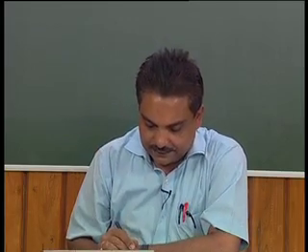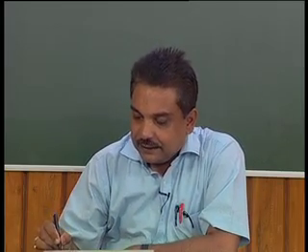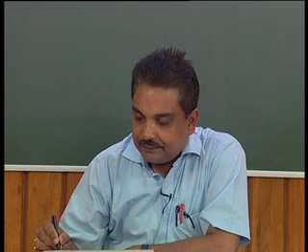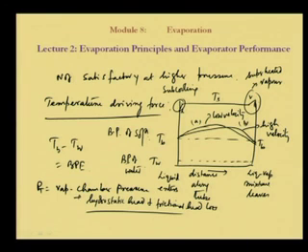Before I tell about that, one thing I should say here: superheated vapor comes in, a little bit superheated, not exactly saturated, because if there is some heat loss, it will be condensed previously itself. So that is not allowed, and some amount of superheat is needed. While it is going out of this heat exchanger, a little bit of subcooling is possible.